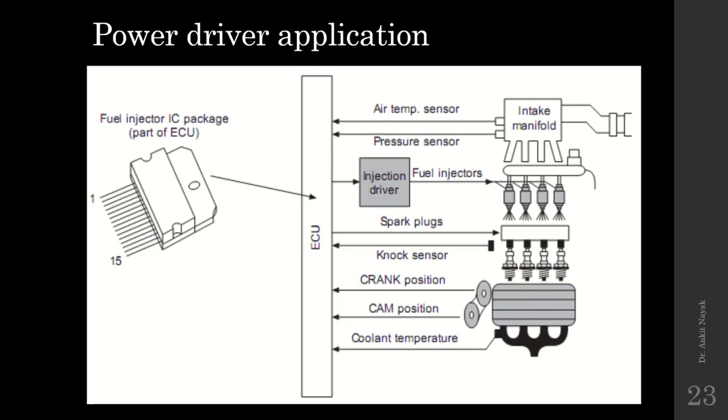Power driver application. Here you can observe the fuel injector IC package and electronic control unit. This will sense the air temperature and give the input value to this ECU. According to that, it will fix different parameters like injection driver and fuel injectors, how much fuel you have to inject inside the cylinder, or in case of a petrol engine, it will control the spark plug, knock sensors to control the knocking, then crank positioning, cam positioning, coolant temperature.